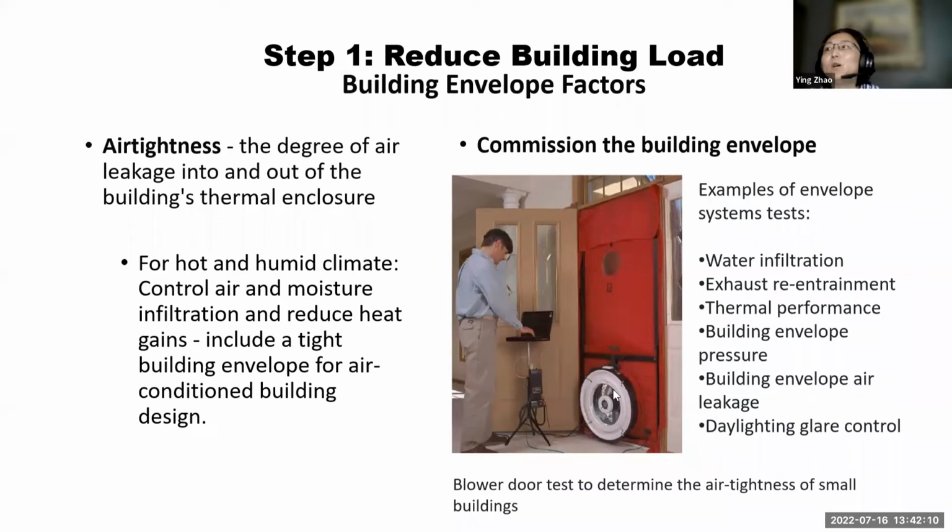So they know the air that goes in through the building cracks will be equal to the air extracted through this fan. So they will know the flow rate of the air infiltration, and they will calculate the tightness status of the space.